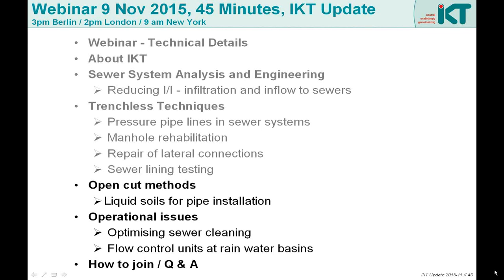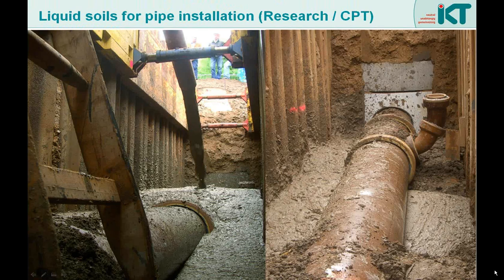Well, from trenchless, let's get to open cut now. Some may think that's not innovative, but it is. As we have discussed before, the pipe-soil system is crucial. Using innovative soils is the key to innovation in open cut methods today. Those liquid soils consist of conventional soil, cement, bentonite, and water.